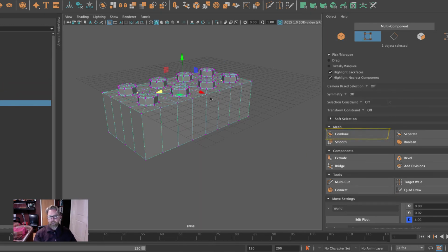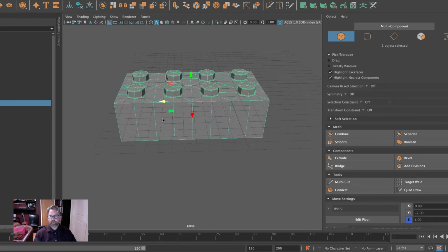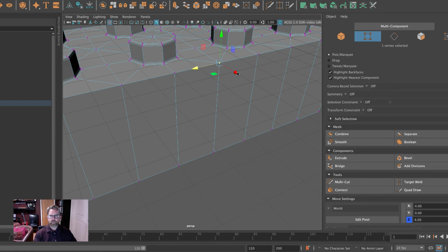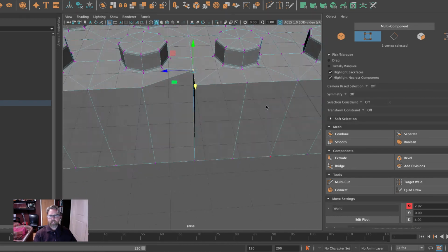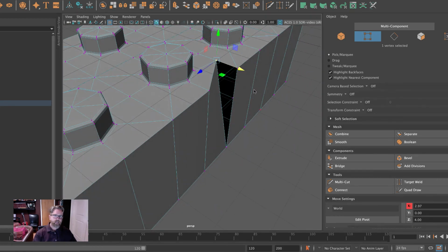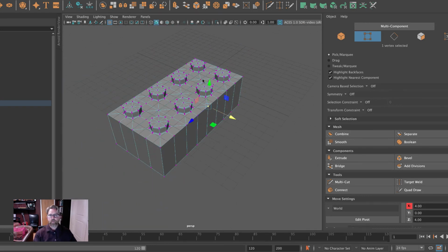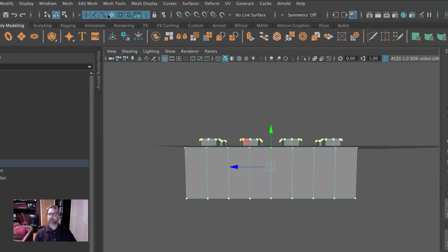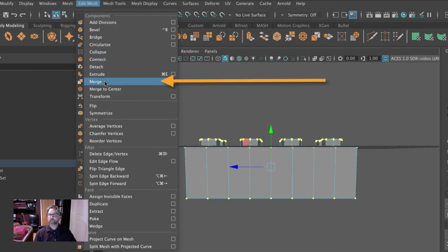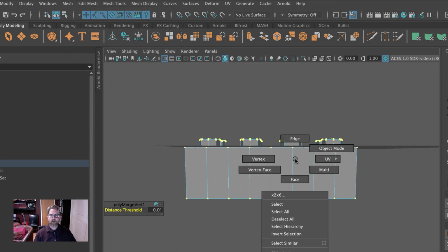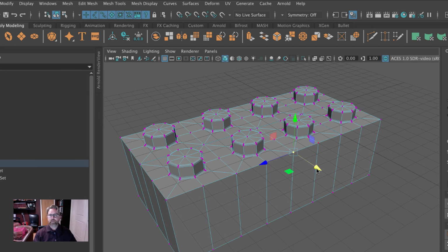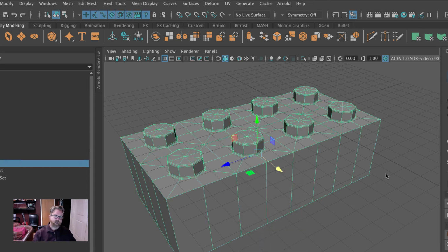You'll recall that while it is a singular shape, these vertices, if we come and just pick one and then use the Move tool, right, we're pulling that out and we can see that they're not welded. We'll grab all of our vertices, even though only the ones in the middle are going to be affected, and we'll say Edit Mesh Merge. And then we'll right click, and you could verify that. You could click on just one, and now when you move it, you see that they're together. So here's our singular shape, and you would export this one, right?